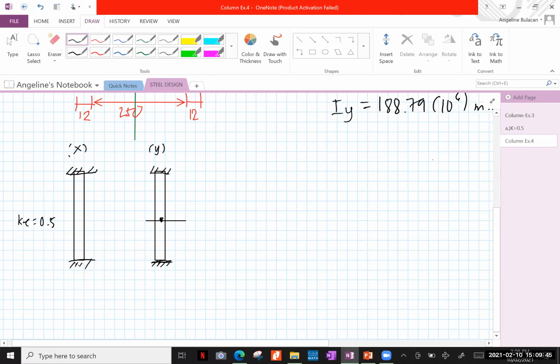And then, ang i-consider lang natin is half ng column. So, yung length is 10 meters. So, for this section, LE is equal to 10 times 0.5. Ito naman, since hinati siya sa gitna, this will be 5 meters. And then, magiging tong fixed support tsaka pin connected. Kapag fixed tsaka pin, ang magiging buckle niya is ganito, diba? Ganyan. So, ang magiging KE natin dito is 0.7.